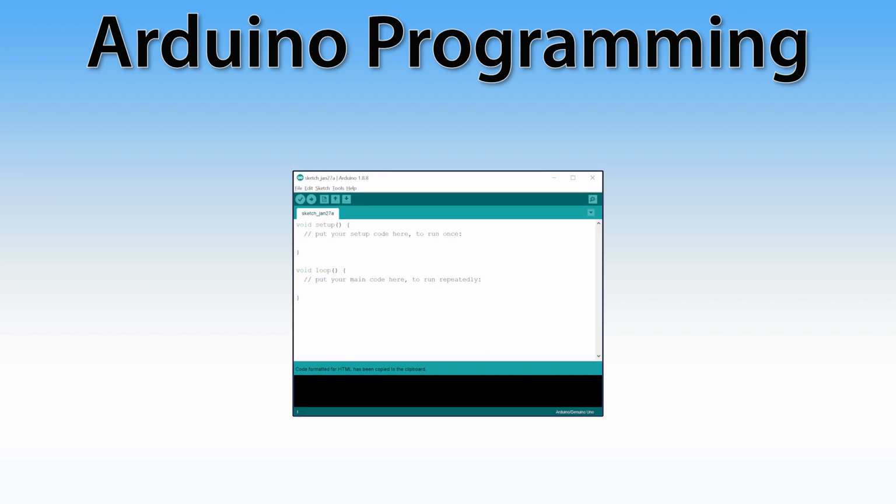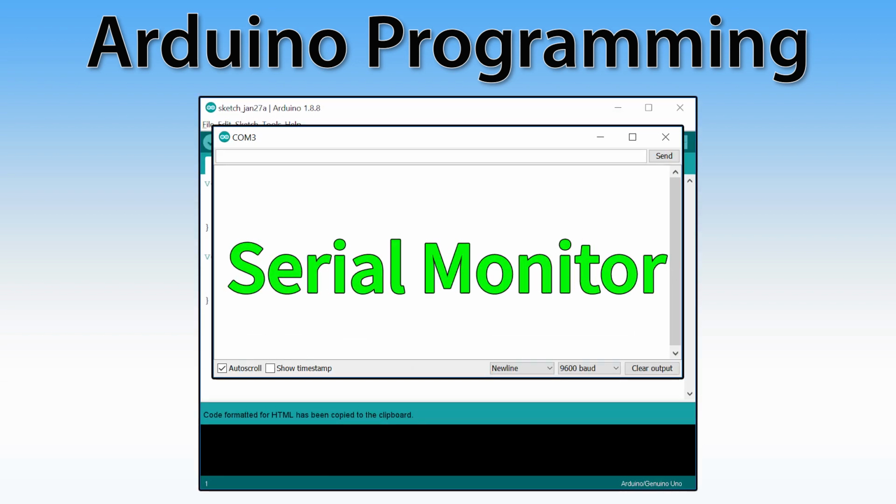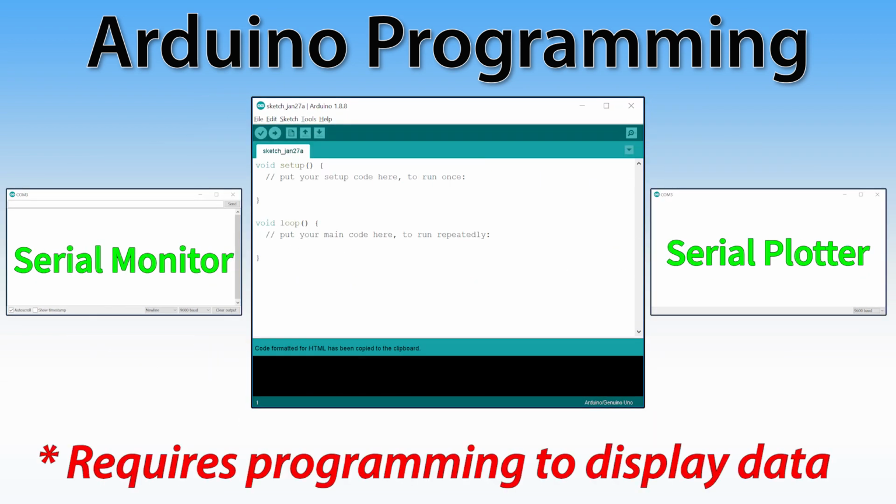With Arduino, there are some debugging tools, like Serial Monitor and Serial Plotter, but this requires prior programming to implement. Only what is programmed to be sent to this serial monitor or other communication method can be evaluated by the troubleshooter. When developing your Arduino project, make sure to implement fault recovery into your project. That will help the technician troubleshoot this process later.